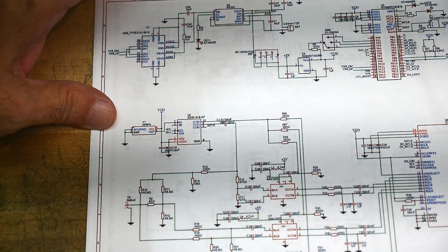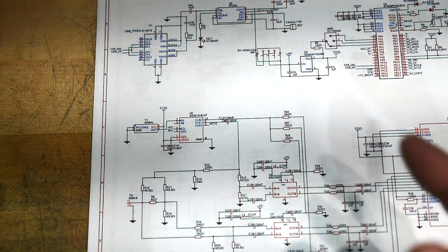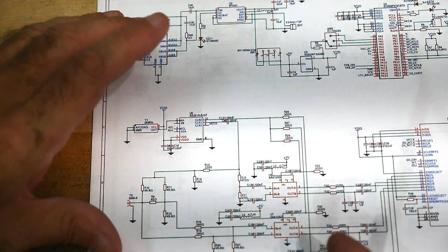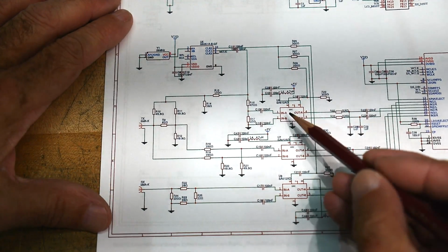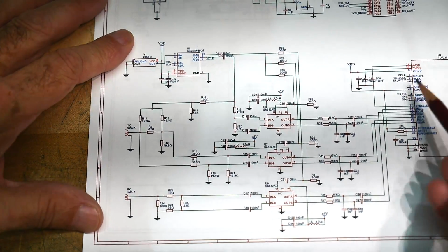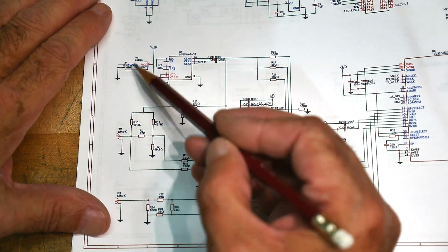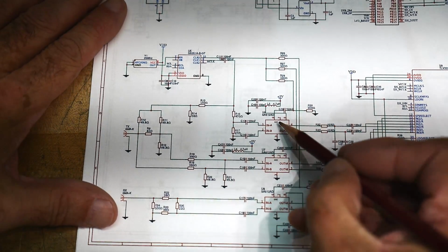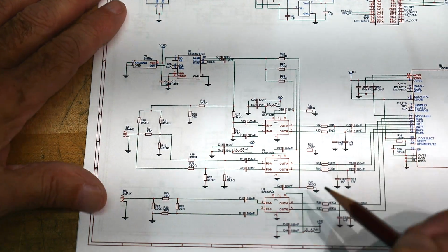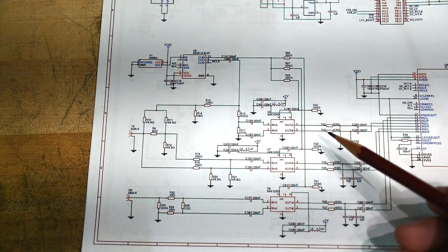Okay. So, what else is inside these NANOVNAs? I drew the poor man's version of these schematics, but what are the actual values used in these things? Here are the three mixers. Here's the sound card chip. Here's the oscillator. The oscillator feeds these three all in phase. They're all mixed exactly in phase, and the sound card has a reference signal coming from that as well.